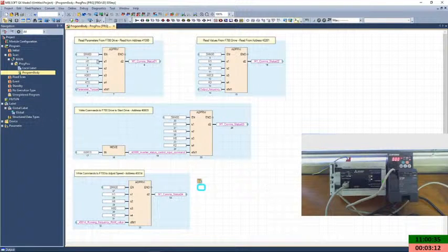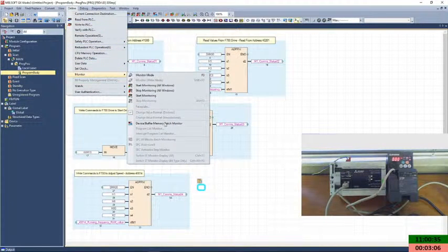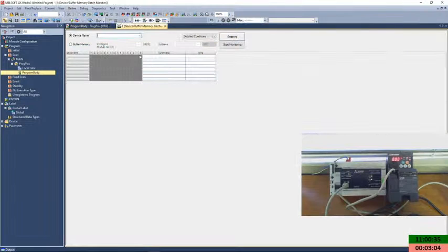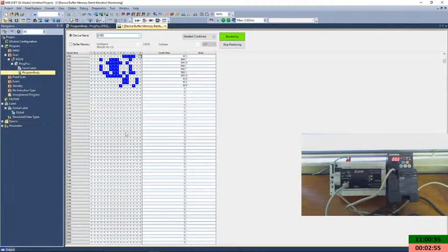So now that we know there's communication happening, now we want to actually start the drive using the PLC. So I'm going to quickly do that for you. We're going to go to D1150. D1150 is where we read the parameters. As you can see, those are the parameters. I don't know them by heart, but parameter 1 is the torque. Parameter 2 there is the maximum speed, and I think parameter 3 is the minimum speed that you can set it at. Okay, so whenever you start up the drive, it will never run slower than 20 Hertz.